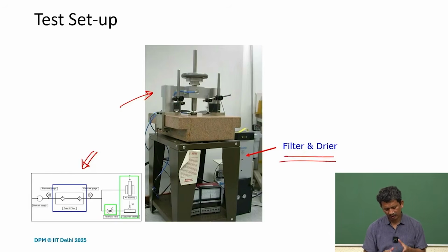So the air which is fed to air bearings has to be prepared. It should be filtered, and it should be dry and oil free. So there are pneumatics involved. Very simple, but we still need to have it. And I think we also understand what the size of the particles is. If they get into the flow, they can easily clog those orifices, because the number we are talking about is 0.2 to 0.8 millimeter of that size.